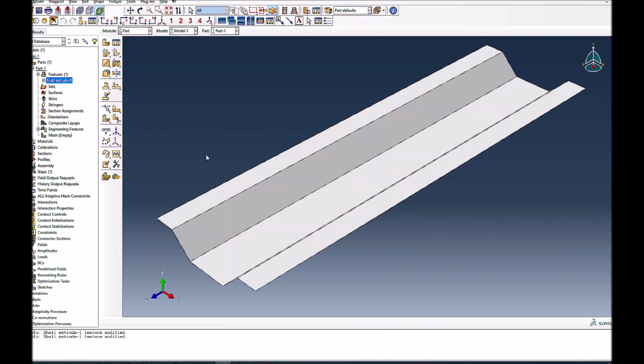So this is it. I don't know if you're familiar with that. I teach a lot of oil and gas related courses. You see corrugated blast walls in many floating offshore structures and also ships, which they use to transport oil and gas offshore. This blast wall is there to separate the dangerous stuff from the non-dangerous stuff. So it's for safety. If a blast happens, this is the first line of defense to keep the structure or stuff safe on the other side of the blast wall. So this is one of the corrugations. You will have a lot of corrugations in the actual blast wall.